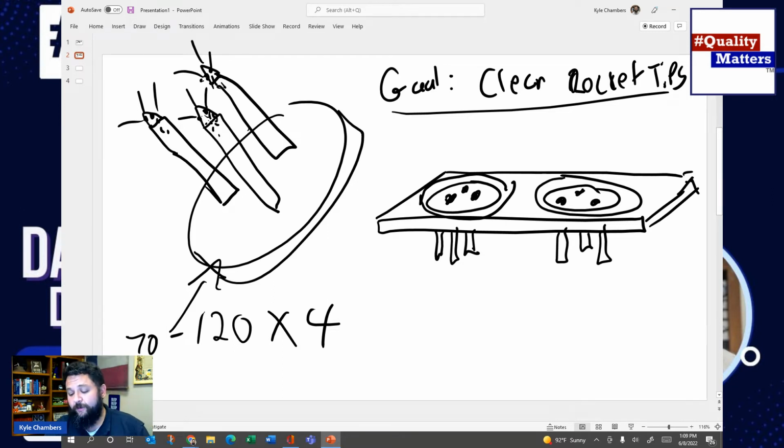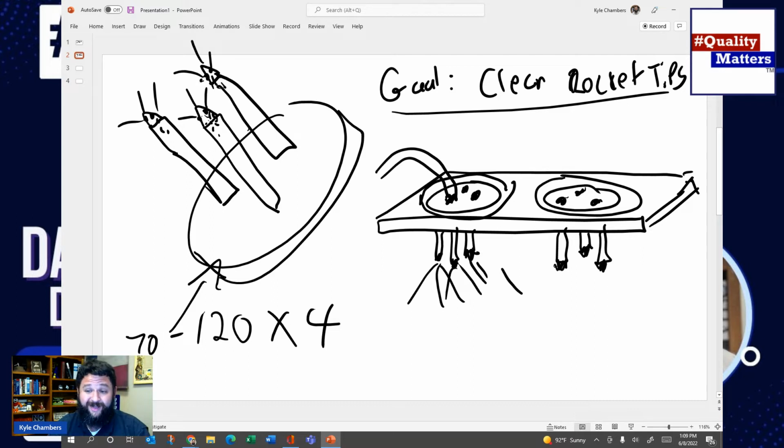And so what they would do is they would put some sort of a caustic in there to clean it out. Now, what they used was, in fact, industrial strength oven cleaner. We would fill these rocket tips full of oven cleaner, and that would do a really darn good job of dissolving all the gunk in here. And you might be thinking, well, Kyle, that's going to dissolve the metal. Some of these super alloys are really hard to affect the chemistry on. But that's what they do. And then they take your average garden hose and run it through so that all that gunk sprays through.